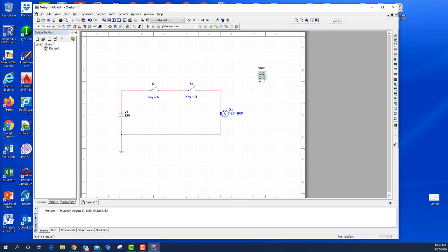So to do that, I'm going to connect it. I'm going to put my positive over here on the positive side, and my negative will go over here to the negative side, just like that. And the multimeter lead color, I'm thankful that it changed it automatically, but had all of these been red where we didn't change it to black, it would have kept that red as well. So I'm glad it changed this to black instead of changing all these to red like it did a while ago. So now we have the multimeter across, what we call a cross or a parallel with the lamp.